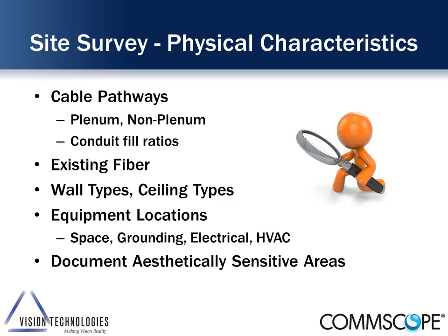So vertically, is there conduit available? And is it full or empty? In a lot of the older buildings, the conduit is full, and you can't really install new cable unless you decommission some of the old cable. That may or may not be possible. And if there aren't vertical pathways, we'd have to create them.